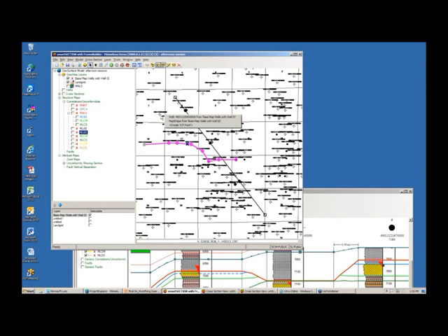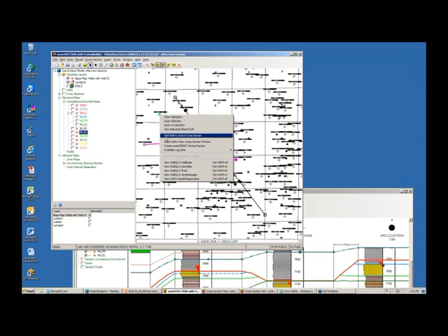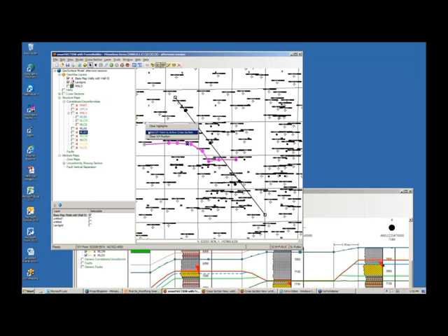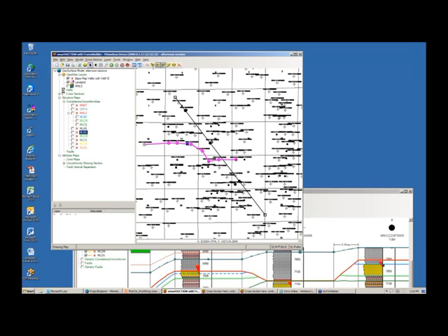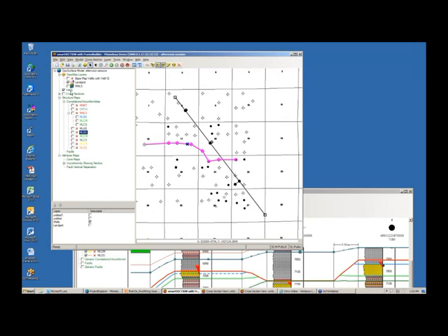So bottom line is you click on a well, you choose its name, you do a right mouse button, you can add it to an active cross-section, open it up in a new cross-section. Yeah, very good question. And you had another, this particular layer, you're using a Geo Atlas layer that has posted text. So it's still going to happen. So if you go to the actual smartSECTION wells layer and make that the only one selectable, then you won't have that problem.